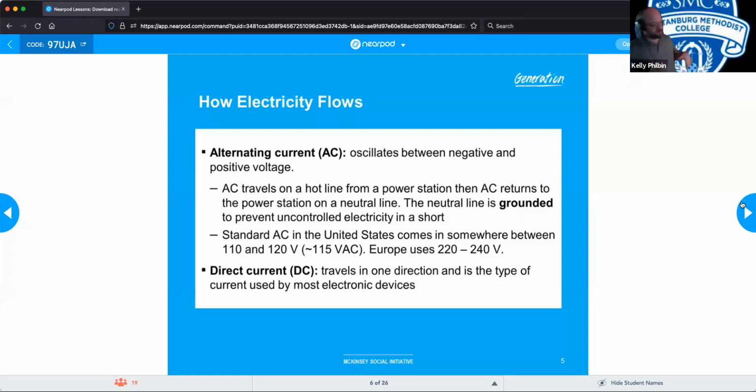Now, if somebody from South America comes here, their selector's set for 220, they plug it into a US receptacle, which is 110, they try to turn it on, there won't be enough juice for the power supply to actually run. So it's a little bit more forgiving coming to the US with a 220, less forgiving if you're going from the US to another country and you don't select it off of 110.